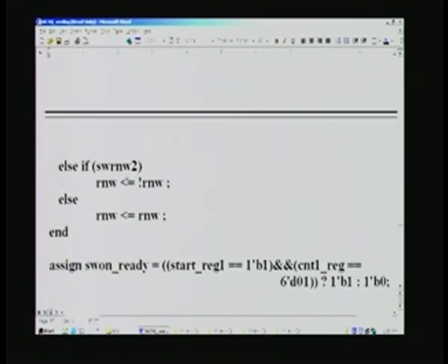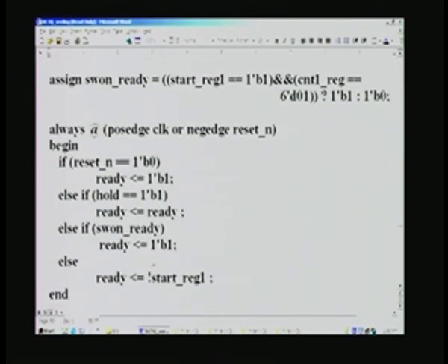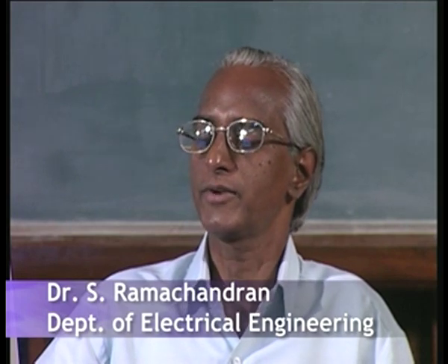And this was for the end of the block we have seen before. If it is the end of the block, we merely invert it, whereas in the previous case it was to differentiate between the very first block and subsequent blocks, corresponding to counter 1 being 0. That is why that trick was played there, and this is done as a routine affair here. Similarly, we create a ready signal, and for this the condition is start must still be 1 and counter 1 is 1, because after this we want to take an action. So, we will continue this in our next lecture. Thank you.